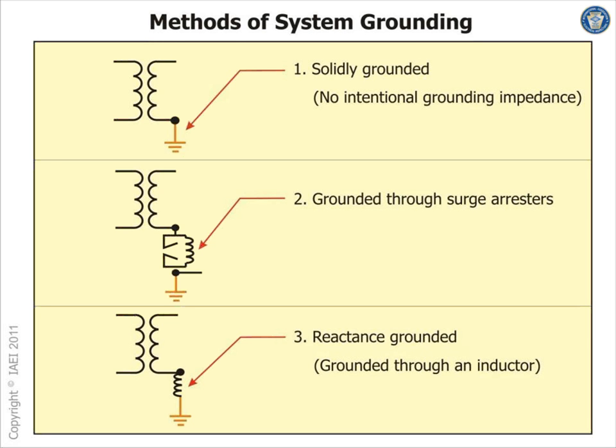That's ungrounded system. The one that we use in between here is called impedance grounded, either reactance or resistance. That guy gives you almost the advantage of both systems. You get your stability to the ground and getting rid of the transient, and at the same time survivability. If you have the first ground fault, you will be able to monitor that ground fault and trip if needed. So that's, I thought, the start point.